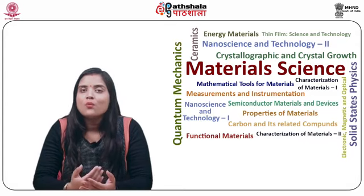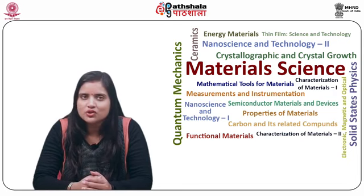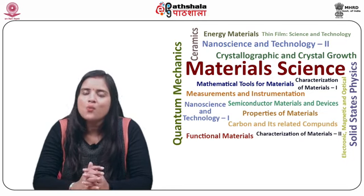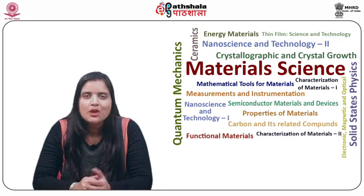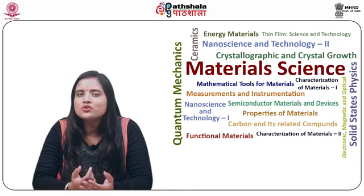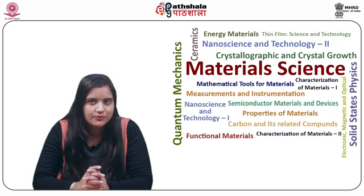The method was devised by Benjamin in the late 1960s when he produced fine uniformly dispersed particles of various oxides such as Al2O3, Y2O3, etc. in nickel-based superalloys which could not be produced by conventional powder metallurgy.